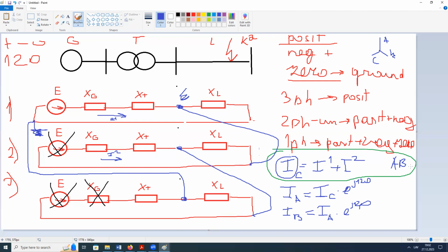But as I said, this is true when we have a complicated network, because here I drew a very simple one. This approach is used for more complicated networks, especially for loops. If we have a series network, we could use a simplification, as we use, for example, in our task, using only three-phase calculation, only the positive sequence.